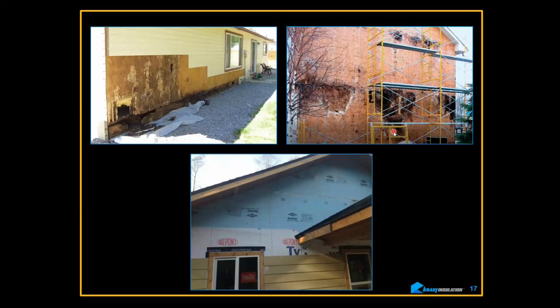This is an interesting one because there were certain areas in here. I don't know what was on the cladding of this system, but obviously certain areas. To me, it looks like what happened is this gap between the OSB all the way across here, where they've got sheets stacked, and you can see the same thing here. It's all happening there, right at that line. So my guess is that warm air got through there, hit up with the cold, condensed on the outside, and there's the problem.